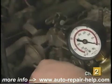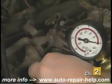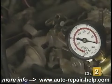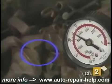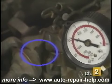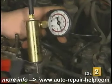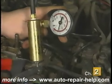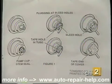Another method for testing and adjusting a choke pull-off is to use a handheld vacuum pump. Simply connect the hand vacuum pump to the choke pull-off and apply 20 inches of vacuum. Once again, the pull-off should move and hold vacuum. If the hand vacuum pump does not hold vacuum and the pull-off does not move, replace the pull-off. Some pull-offs have a small bleed hole on the backside that must be covered with a piece of tape or your finger during testing.